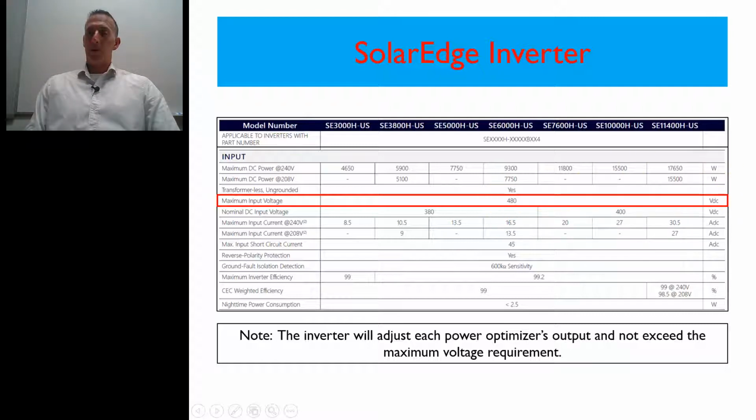So just remember, we're combining all this information together. We're getting the information from the optimizers, or converters as the code calls it, off those spec sheets, coupling that with the inverter, and it determines what the maximum output is.